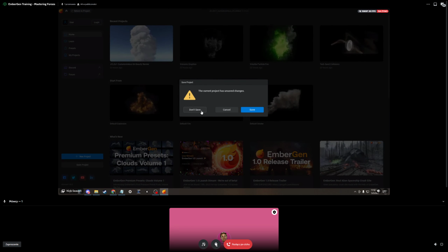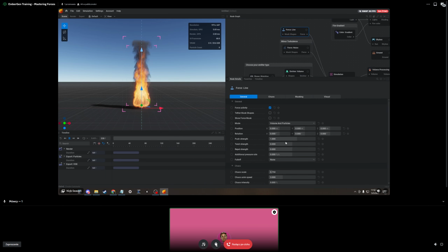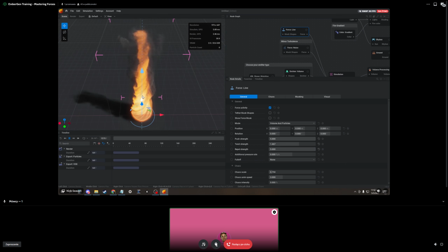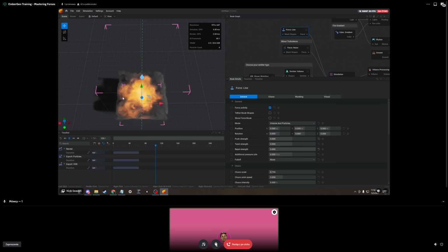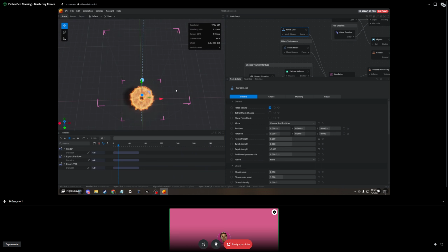So we'll go back to our default. And let's see if there's anything else on line force to cover. I don't necessarily think so. You do have twisting and pushing and repelling, and twisting is being shown with your different lines. So you have your main gizmo here to see what's happening, and then you have a repel strength. We don't have a gizmo for that, but the way to think of it is if you repel, all of your vectors are going to be pointing away from the line. So if we have no push strength or anything, and we repel, you can see that it's pushing things outwards from the simulation. And then if we have negative repelling force, it's going to suck things in.